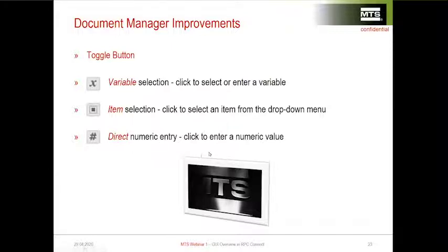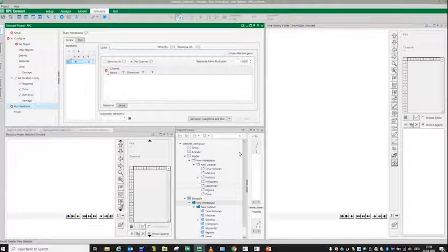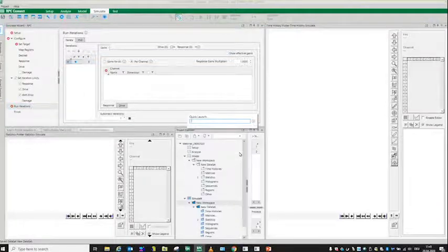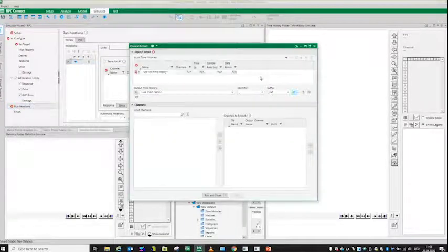So if you want to use that one, let's go for example again with channel extract, because now we are all familiar with that. I use my time history. I have now switched the stage, so sorry for that. The imported file is not available. But to show you the behavior of the button, I can say, okay, the output file now, if I click on that one, it will ask me now for a variable. So if I define a variable called test drive number 1, the output name of my file will be called test drive number 1 plus identifier plus X.